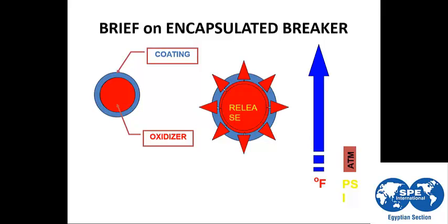If you break this viscosity early, the proppant will start to settle down and you will get a screen out. Also, if you delay the breaking too much, you will take so much time waiting for the frac fluid to break, for the breaker activation, before you can proceed with your cleanout job. So the time of breaking is critical.